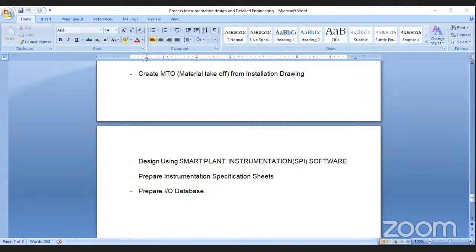So what is that logic? When to start a pump, when to stop a pump, or when to move a sensor. When to stop a conveyor. All these things come under PLC logic development. As a designer, you should be able to develop the logic, and that logic will be programmed by the PLC vendor. Of course, you can also do it yourself if you understand Allen Bradley or other logics; we'll use it here for programming purposes.